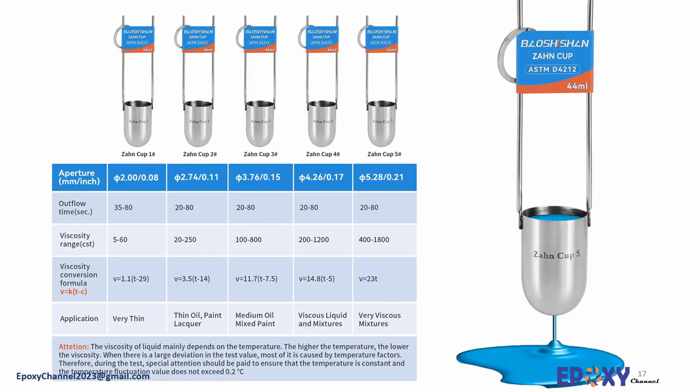The same principle applies to other cup type viscosity measurements. And tables or charts are provided by the supplier of the cup and should be used as references. Here, the design of various Zahn cups has been depicted for your reference. Again, here based on the viscosity expectations, a cup with proper nozzle size is chosen.